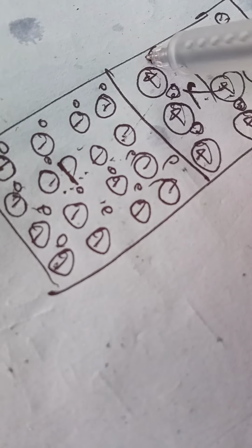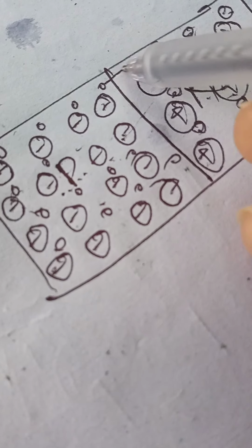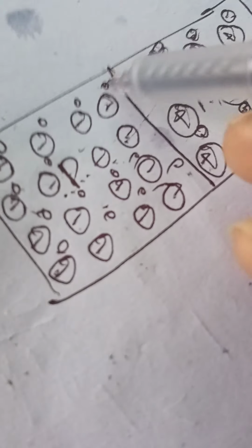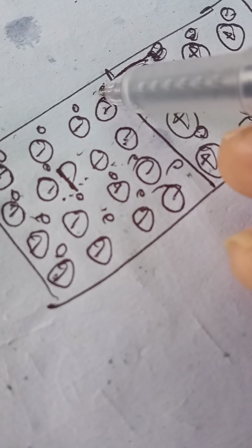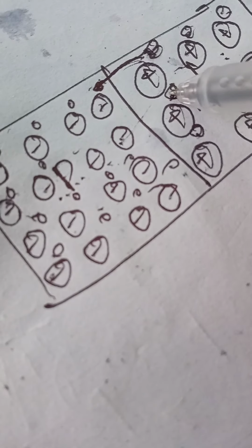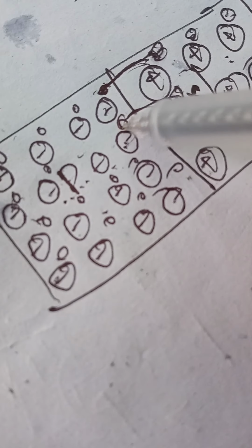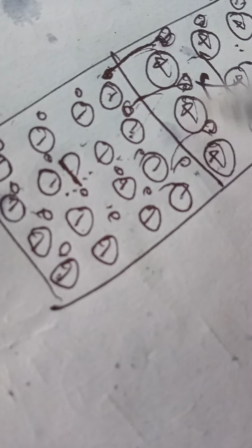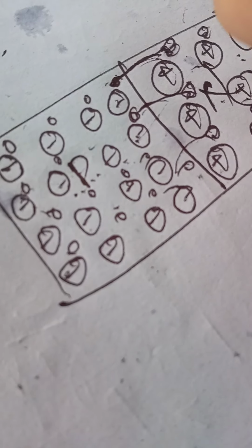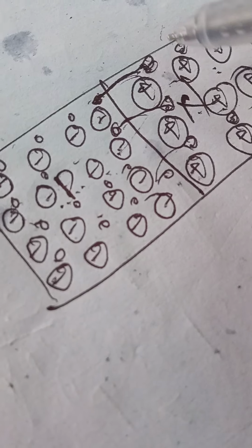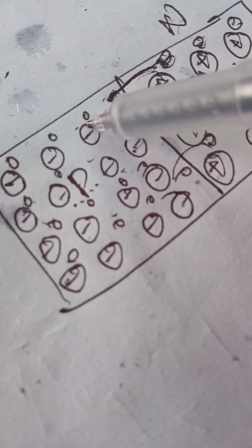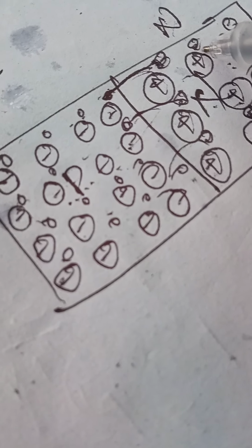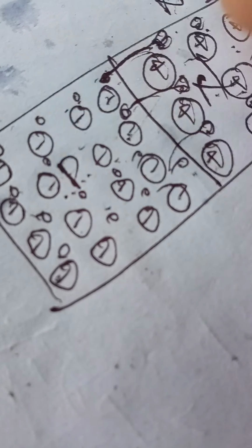The electron which is present nearest to the junction starts attracting towards this hole, diffuses from one side to the other side, and becomes neutral, isn't it? Similarly, this particular electron gets combined with this hole and becomes neutral. It also combines with this hole and becomes neutral. So likewise, slowly all the majority carriers in the n-type start diffusing to the other side, and similarly holes from the p-type start diffusing to the other side of the junction, and they get recombined with the opposite polarity. So as a result, what happened?